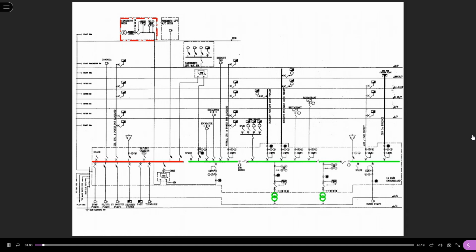Okay, so in this diagram, as shown in the center line box here, this is the main LV switchboard. The main LV switchboard receives the electricity from the transformer, which has been stepped down already. So the voltage output from the main LV switchboard is 380 volt three phase and 220 volt single phase. All right.